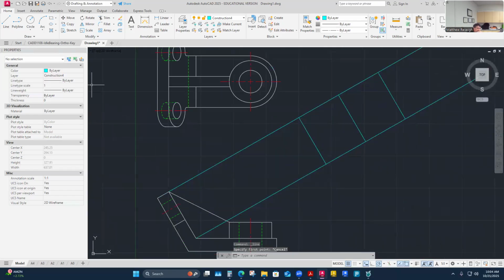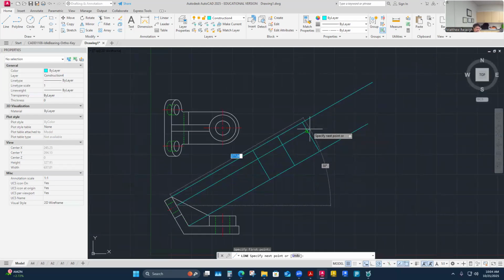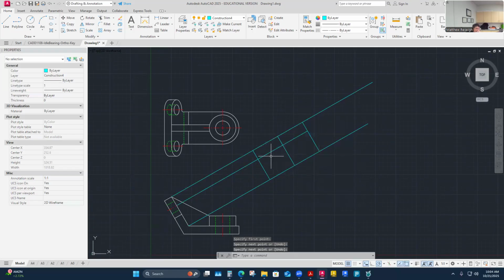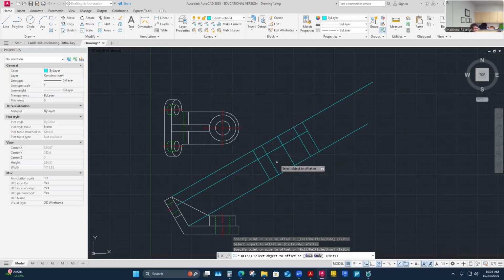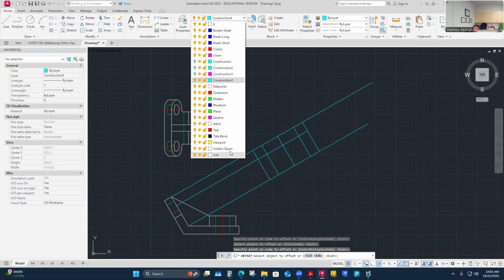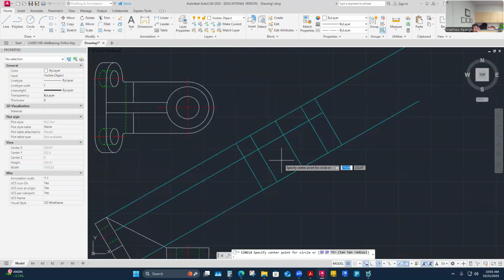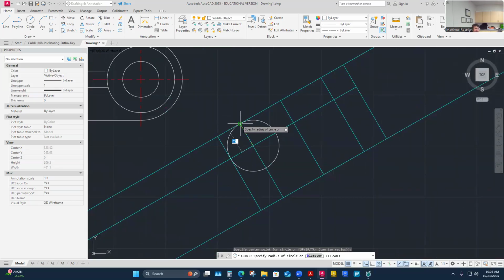I can definitely project other stuff from there though. Like the center of this is right here, right? So it would project across. Make sure I'm on those snaps. That's the center line. They're spaced 90 apart from here, so I feel like I can offset this 45 again. I might do another offset of 45 and say this and this. There's the center of the circles and the radiuses, so I think I can start to piece this together with visible line work. I would have a circle here.